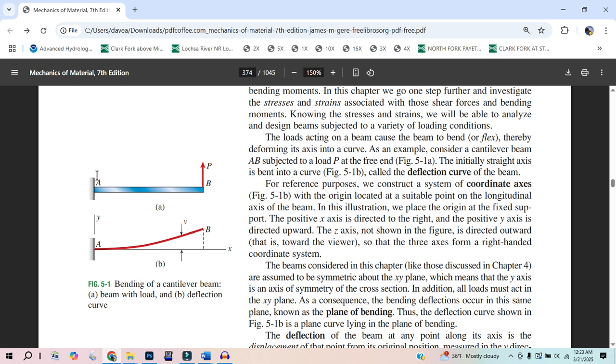So if we have 29,000 pounds on a 1-inch steel bar, we could shear through it, or we could just barely hold on to that strength. Now, if we come over here and apply a downward load, and this is just even a meter out, how much load could we put on that before the bending part, before this frowning, before we get so much crunching in on the bottom that the pressures get bigger than 58,000, and then the top, the pressures and tension get bigger than 58,000? Those are going to happen at the same time if this is a rectangular cross section, you know what I mean?